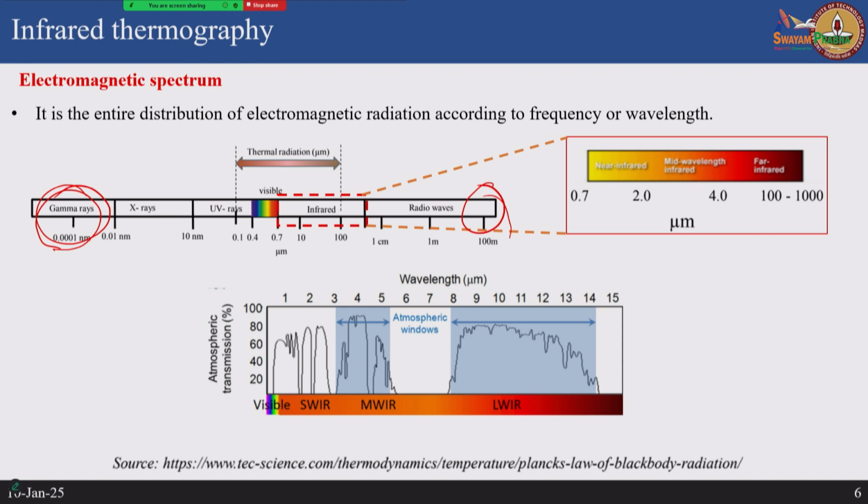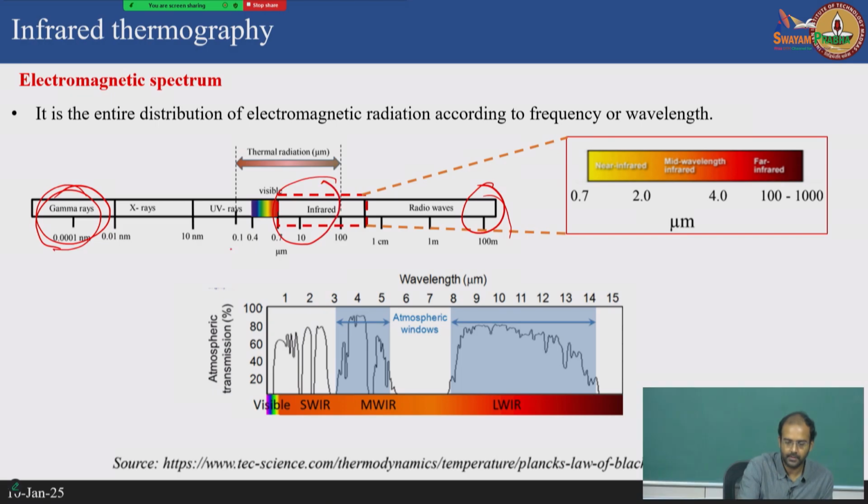What we are talking about as thermal radiation is usually part of the solar spectrum, where part of the UV spectrum is covered, and then it covers the visible wavelength and, to a great extent, the infrared band. Generally, from 0.1 micrometer to 100 micrometer is considered the bandwidth of thermal radiation. So, why should we consider only this as thermal radiation? Everything is electromagnetic waves, of course, and microwaves also produce heat when we use an oven, but the reason is that it is more related to the solar spectrum.